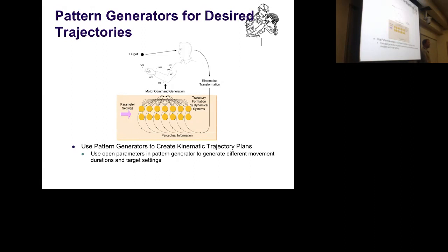That was basically taken as a simple example of how to generate patterns, like locomotion patterns, how to move forward. And what's nice about these things, if you go into these representations of differential equations, you can actually change the pattern online by adding something which people call coupling terms, which are this x1 or x2. Like if I put a coupling term in here, which might be negative, then I basically push the system in a completely different direction. And this way you can think about, well, wouldn't it be nice to have these systems which automatically react maybe to some visual or perceptual input in general, and then kind of go around obstacles automatically and do useful things.